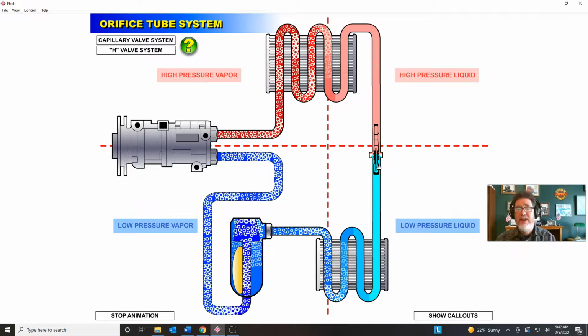So you hear this hissing sound for about, I would say, around 30 seconds. And that's telling you that the system is equalizing. You could watch your gauges, and as the system is running, let's say your high side is at 200 psi and your low side is at 25. In that 30 seconds of equalization, you should be able to see your high side dropping down and then your low side going up until the pressure is equalized to whatever the underhood ambient temperature is.